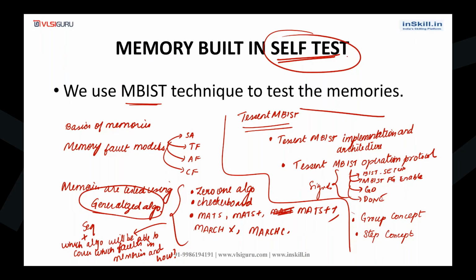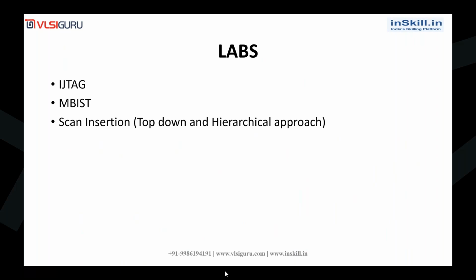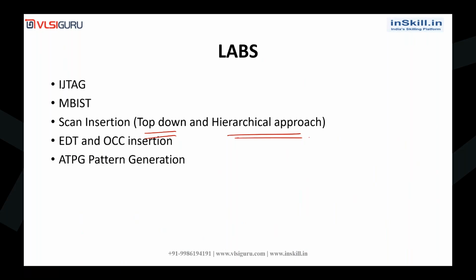Whatever I had told earlier was the theoretical part. In labs, we'll be covering IJTAG, MBIST, and scan insertion. There are two approaches in scan: one is top down and the other is the hierarchical scan approach. We'll cover both approaches, EDT and OCC insertion, ATPG pattern generation, and ATPG and MBIST simulations.